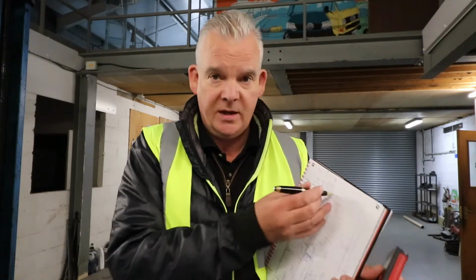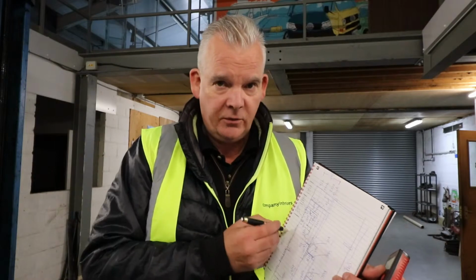So what we've got to do first of all is get the survey done. We've got to get some drawings produced. So let me talk you through how I do that. First of all, I will start off with my pad, I will start off with my laser, and I will start going around the building and just making sure that we've got all the dimensions in that we're going to need. We always start off with the overall length, the overall width.